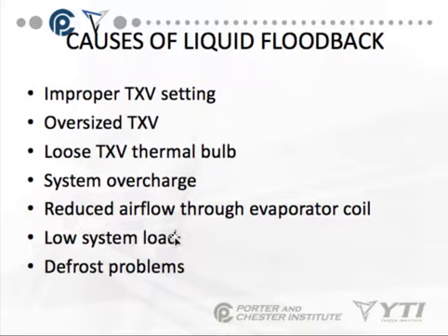It's allowing the system to be too far open. We might have a system overcharge. Too much refrigerant in the system is not boiling off before it reaches the compressor. We might have a restriction in the airflow through the evaporator coil. Again, reducing the refrigerant from being boiled off and allowing liquid refrigerant back to the evaporator coil.